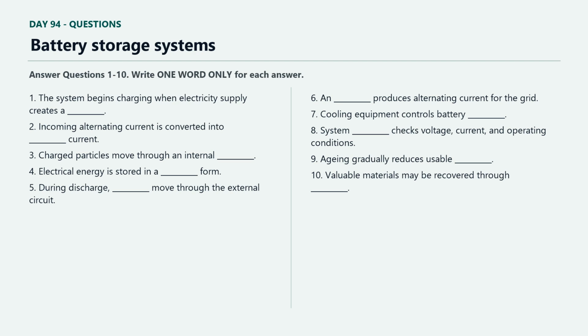A battery management system compares individual cells and estimates how much energy can be accepted or delivered safely. If one cell approaches a limit before the others, the complete pack may need to reduce its operating range. Balancing circuits help bring cell states closer together, although they cannot repair physical damage. Alarms can trigger a reduced power mode, controlled shutdown, or emergency isolation.